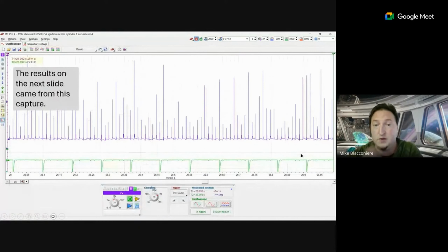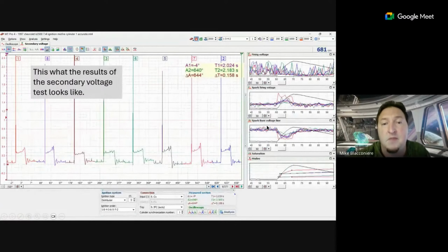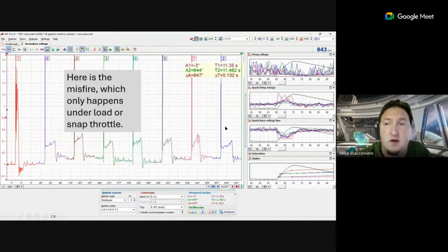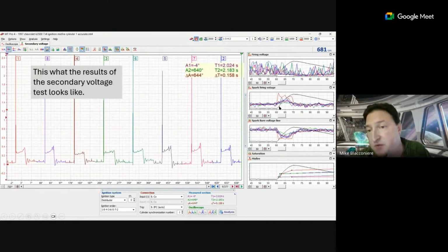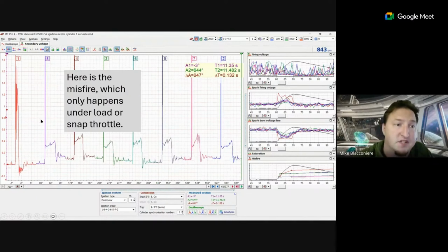So we go back here, you can see that's a 45-second capture, less than a minute to run this analysis. We can look over here and go, I'm going to jump to frame 61 and see what's going on. Jump to frame 61, see this, and I know what's going on with the engine, with the ignition system, and why the misfire is happening in 5 or 10 minutes. So this doesn't take a bunch of time, and it's a simple, easy, fast test.